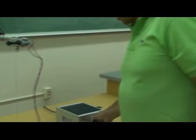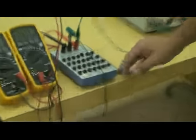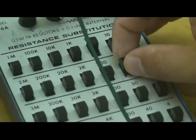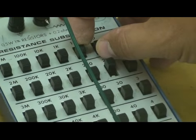So you come over here, and my original resistance, if you can zoom in, my original resistance where I ran the generator, it was 100. So I'm going to reduce the original resistance. I'm going to raise the 20 here, lower the resistance. So now the current should go up.